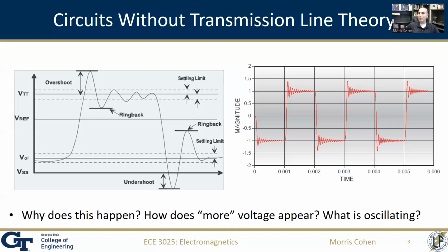And this is basically evidence of the fact that there's a physical separation between the source and the receiver, in this case, between the oscilloscope and whatever it is in your circuit that's powering the voltage. And so you can actually measure the finite back and forth delays. If you take that velocity and divide it by the distances, that's going to correspond roughly to the time scale of these oscillations, and that's not going to be a coincidence. So let's dive into how exactly this happens throughout this lecture and try to build up the physics and the understanding of that.